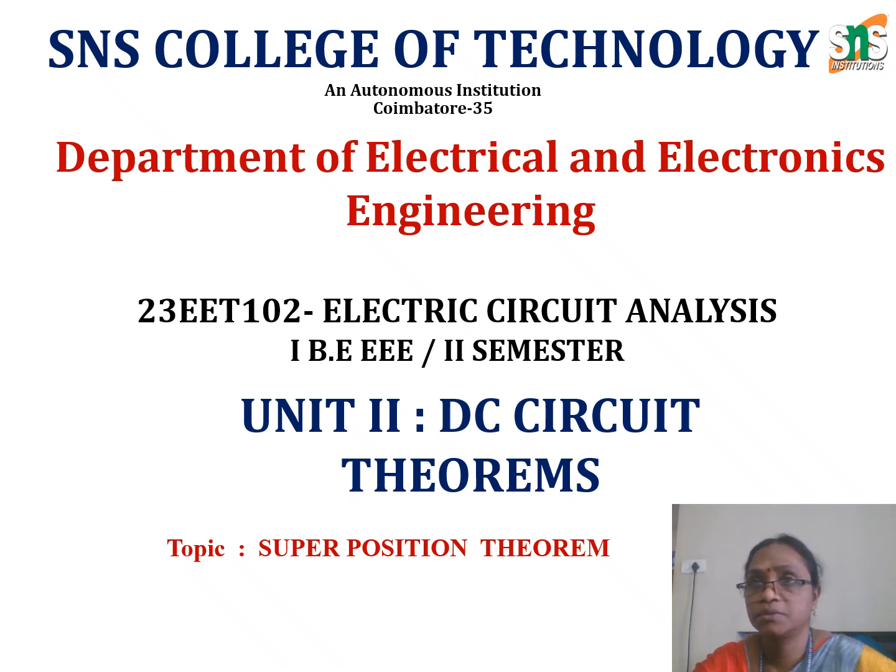In the superposition theorem, we already know that if we are considering the current source, the voltage source will be short circuit. If you are considering the voltage source, the current source will be open circuit. We apply the superposition theorem when more than two sources are available in the network, to find the total current.